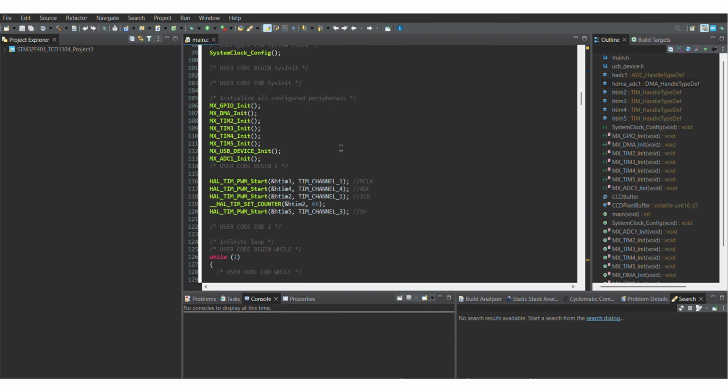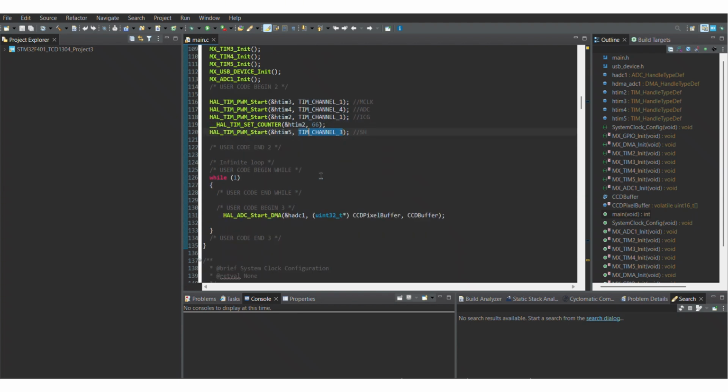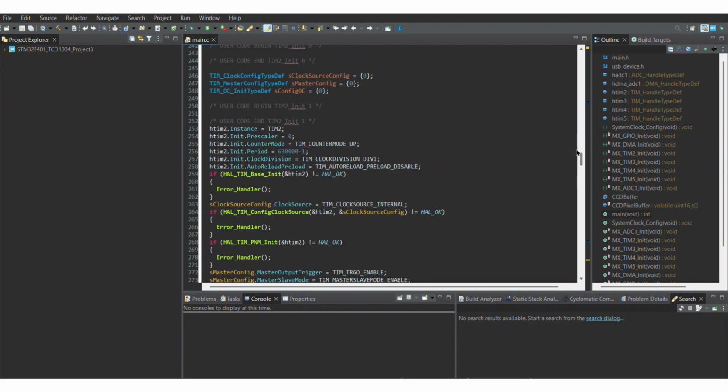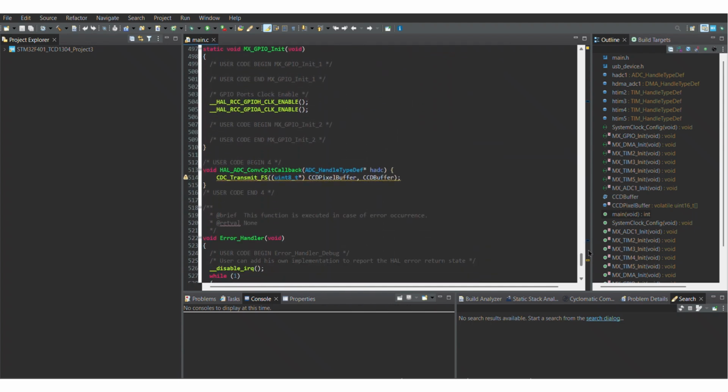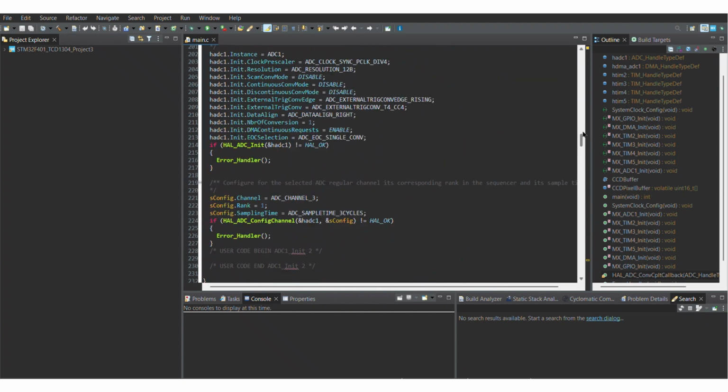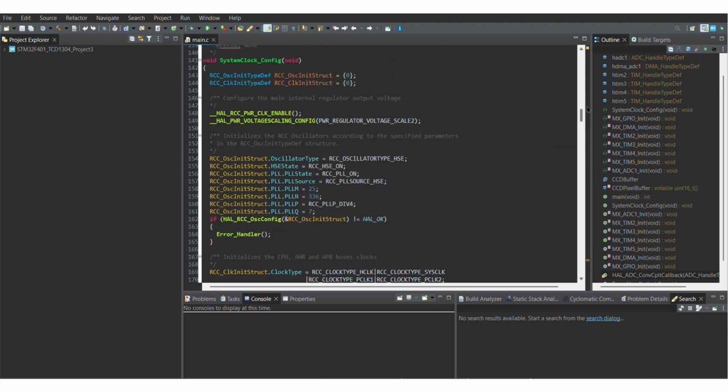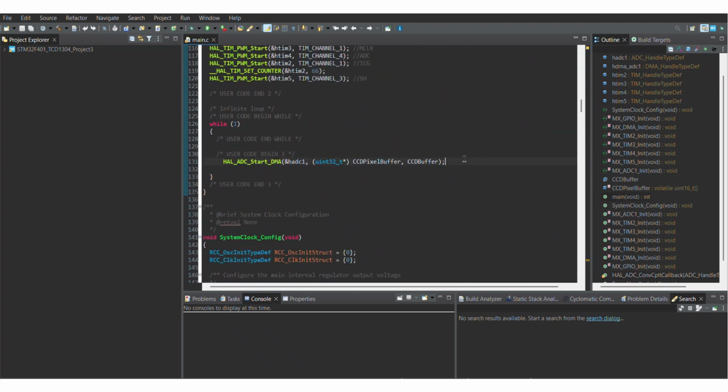Here we have the initialization of all peripherals used, as well as the start of the 4 timers and the delay used before the shift gate is begun. Here we have the while loop, which is the command that begins to send the data. And if we scroll down here, you can see what is being called within the while loop. This transmits the data using the VCP connection over the USB cord. So again, that's here in the while loop, which will send all the data.